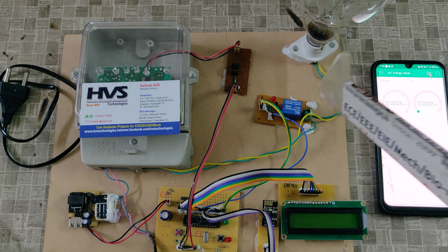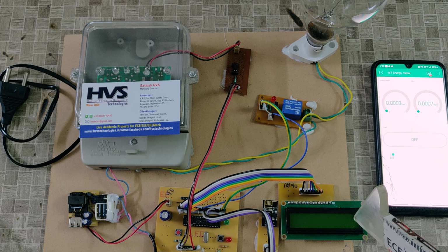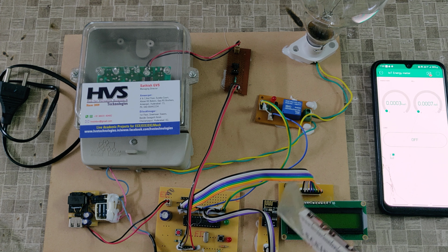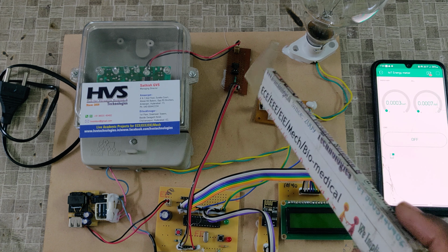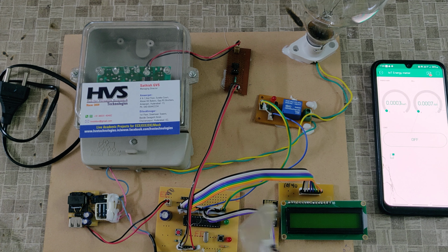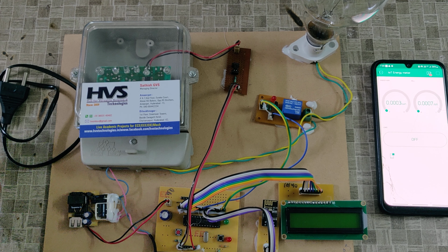Next is the electromagnetic relay to control this load, the LCD display to continuously display the status, and a Wi-Fi module to pass information to and get information from this Blynk application. The interfacing connections are: A4 pin to the optocoupler, relay at B0, C6 and C7 for the ESP8266 module, and the LCD on B4 to B7. The main controller is the PIC16F73, and this fault switch is interfaced at the C3 pin.